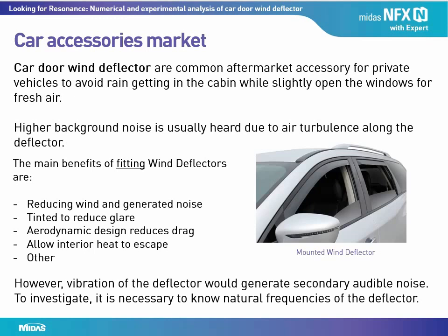In addition, knowing the mode shapes of the deflector provides useful information for optimizing the structure. For instance, we may add a rib here or there to strengthen the deflector to move a resonance to a different frequency or minimize its vibration level. We could also change the mounting points to tweak the mode shape to move the resonance spots far away from your ear, closer to the window, so that you can hear lower noise.